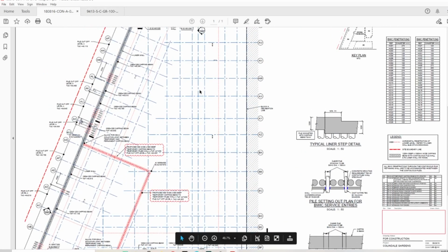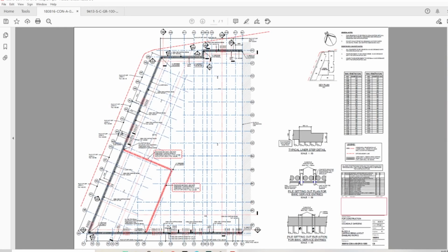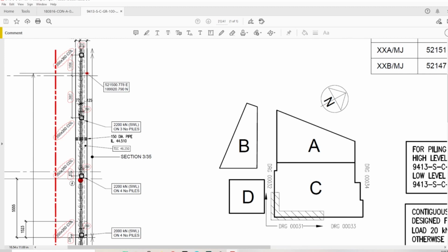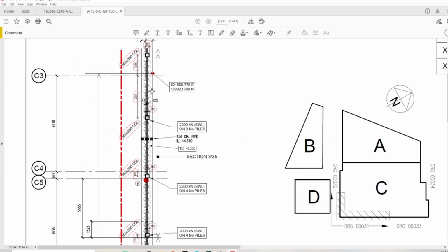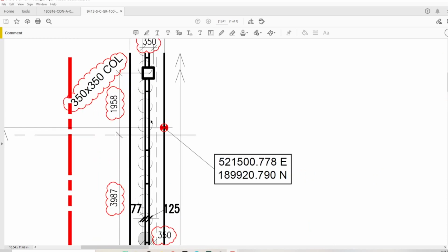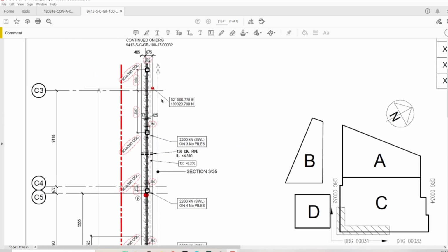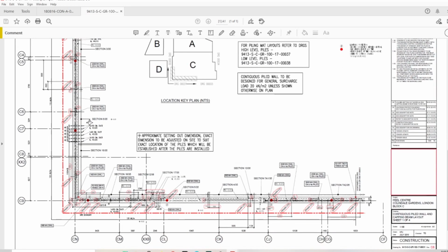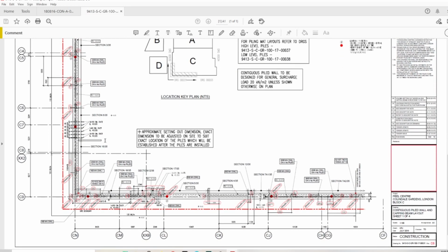As you can see, this is on one drawing, and the information is quite okay, but this one is split in 4 drawings. You do get information about the columns here, which is actually better, because when you're looking at the capping beam drawings, you know there is something. There is some upstand here as well. You see these 2 lines. So this gives you more information on the plan, and this is better really. Especially if you've got no experience and you take only the capping beam drawing, you can miss these things.